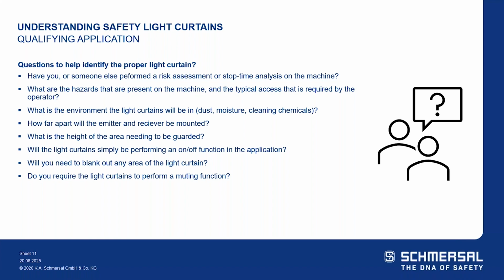What are the hazards that are present on the machine and the typical access that is required by the operator? What is the environment the light curtains will be in? Is it dusty? Is it moisture? Is it cleaning chemicals? Is it a high pressure hot water IP69 environment? Is it a hygienic environment in the food and beverage and pharmaceutical industry?